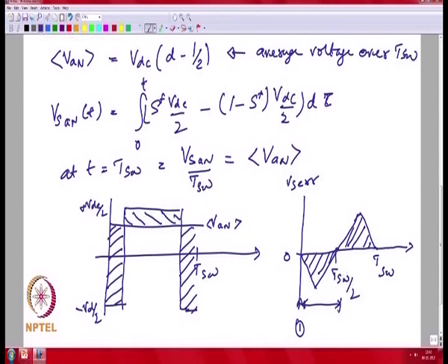So many times people use a zero order hold model for the inverter with the subsequent analog filter, etc. In case there is sufficient separation between your switching frequency and your control frequency, people might even be justified in ignoring such delay effects.